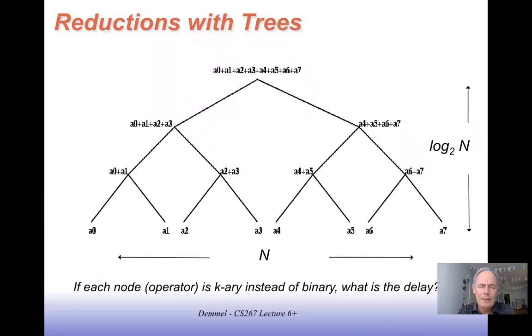If we had an adder that had a delay proportional to n instead of log n, we would have at least 64 gate delays and more actually for an add operation, and it wouldn't fit within one clock cycle, or we'd have to have a very slow clock. If we can make it a log, the log of 64 is 6, so it's going to be a much smaller number. We're going to have a much higher clock frequency possible. So logs are nice, particularly if we scale up to bigger numbers. Logs get much better than n, obviously.